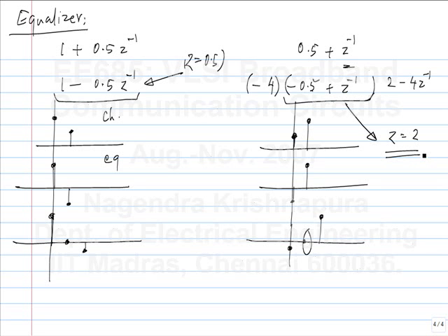Actually, we have not discussed one type of equalizer which can only do post-cursor ISI, right? That's a decision feedback equalizer. So in combination with that, you can use an equalizer that corrects only for precursor ISI. So in that case, you would have a right half plane or outside the unit circle zero. It's just to know what you get, right? For instance, that will give you an idea of the range of the coefficients. So if you see a response and you see a lot of precursor, you know that you have to make some circuit that gives you a right half plane zero.